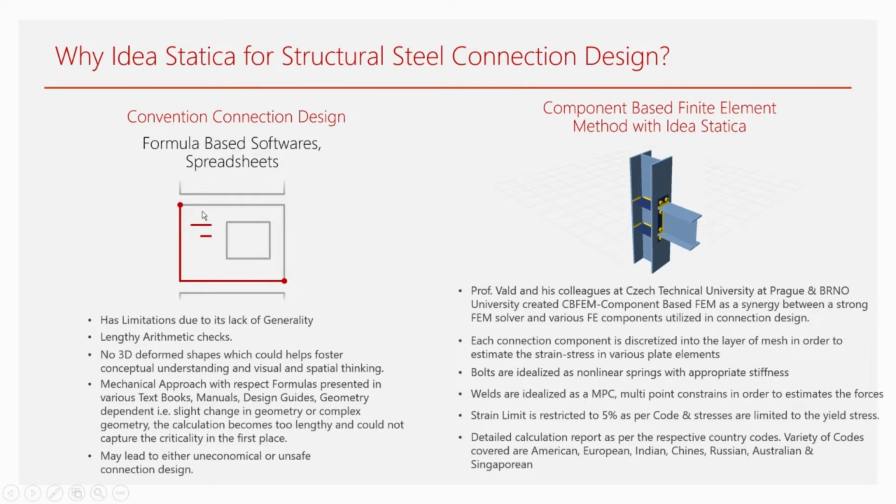This approach is somewhat mechanistic or mechanical, with regard to the formulas presented in a variety of textbooks, manuals, and design guides, and it is a geometry-dependent approach. When there is a slight change in the geometry, it will not work, or you have to update or add some checks manually to satisfy the connection design. So this approach sometimes leads to uneconomical or unsafe design, because it doesn't capture the criticality in the first place.